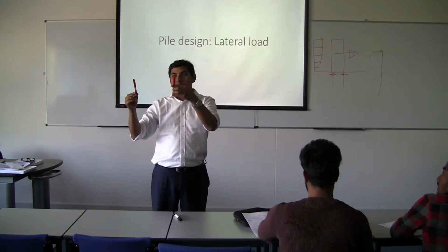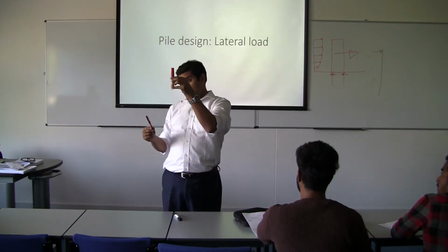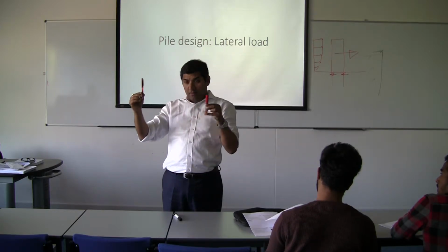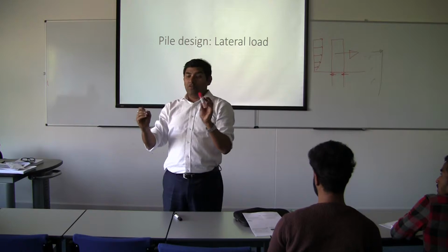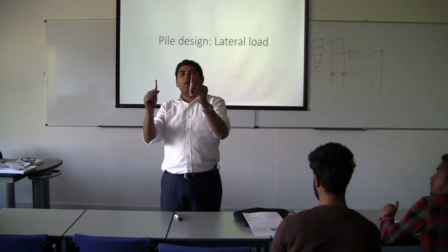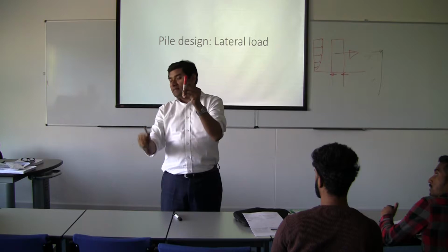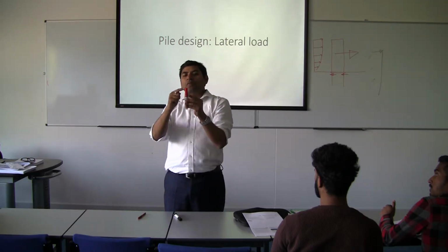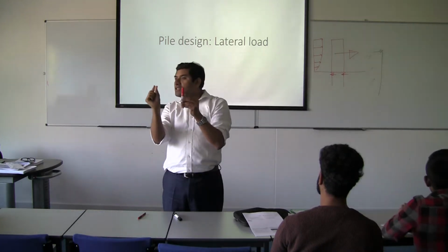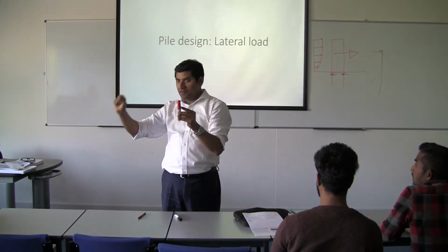In what ways? The short one will be more rigid. So it will probably be more rotational, whereas the longer one will have more flexure. Yes. So, technically, what do you mean by a pile failing under lateral load? Failing means this: you keep on applying load, and at a certain point, a small change in load will give a big change in displacement. That's by definition a failure.